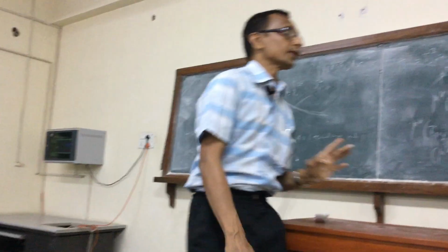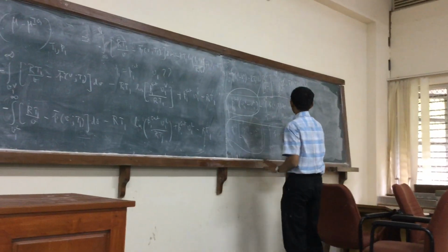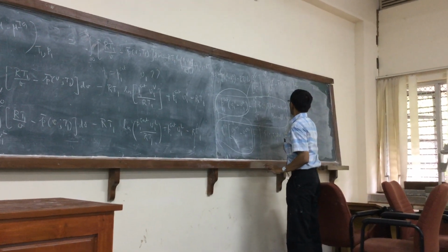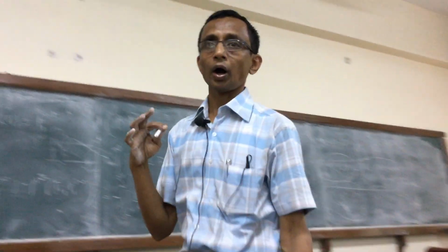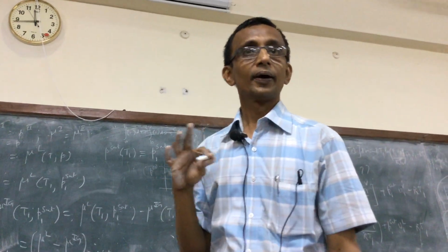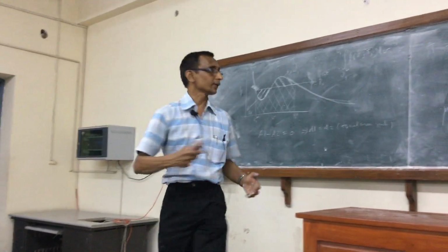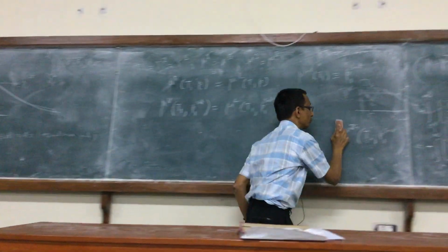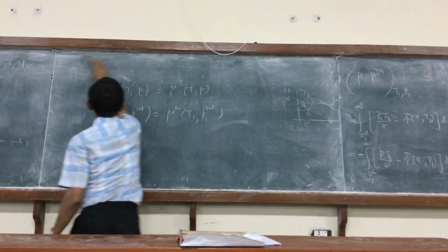But the fact that this quantity here is actually A1 minus A2 will help us come up with the correct algorithm to determine the saturation. You see how it is helping, this geometrical picture is also helping in getting the algorithm right. We see now how the algorithm will proceed to calculate the saturation pressure.